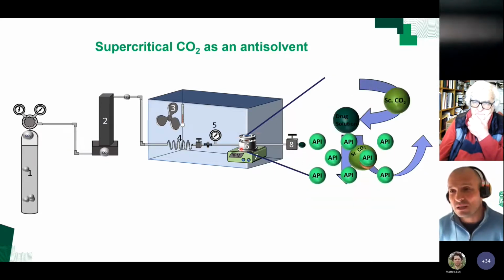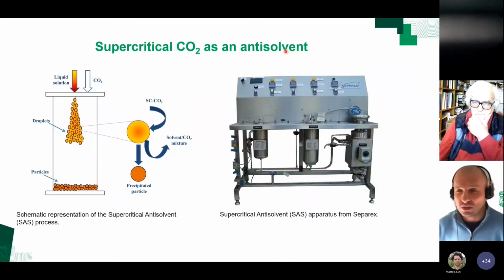And there's a semi-continuous approach also using an anti-solvent, which is called SAS. This is a method for which some CDMOs have generated equipment over the last 10 or 20 years, but again, no implementation in the pharma industry. It also uses CO2 as an anti-solvent, but here CO2 is pumped into a high pressure chamber, and the liquid solution as well through a nozzle. This nozzle will push the solution, which is sprayed into droplets. Those droplets go inside a high pressure chamber. That means that the CO2 will penetrate the droplets, extract the solvent, supersaturate the solution, and then the particles will eventually precipitate here.